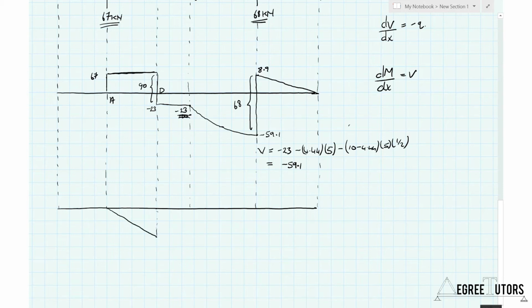Now I don't know what the magnitude of the bending moment is at that point. I just know that it starts off at 0 here and goes in a straight line to some point down here. By looking at the structure and the loading applied to it, I know it's the underside of that structure that will experience tension. And because I draw my bending moment diagrams on the tension face of the structure, I know to draw the line coming down on the underside, or the tension face.